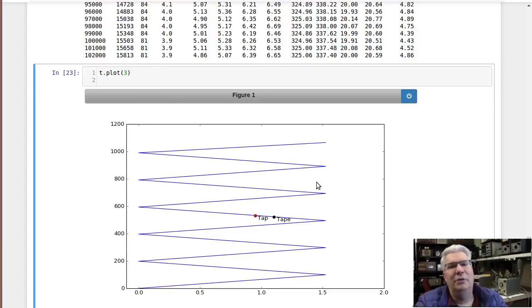Okay, so here we go. This is the high voltage wire. It's winding number 3. So you can see we go along here, and then we're going to stop here for the tap, and then we're going to stop 10 turns later for the tap. And so this is just a visual representation of what's actually going to happen.